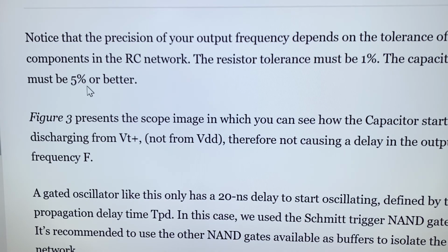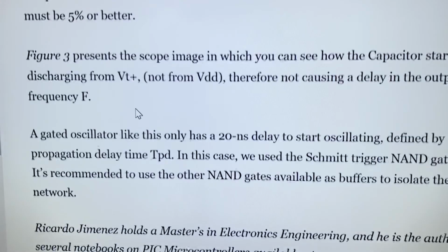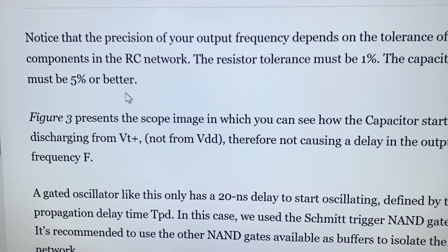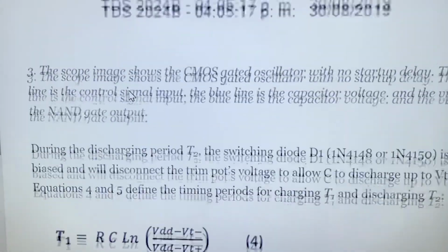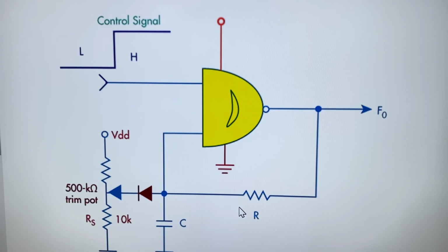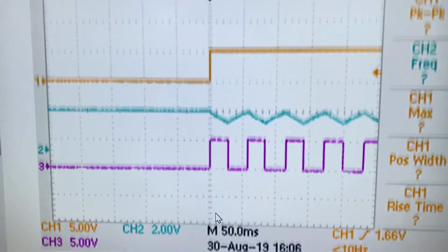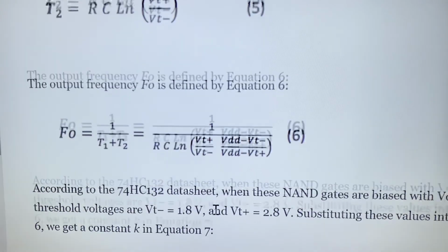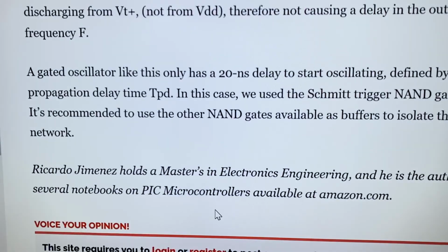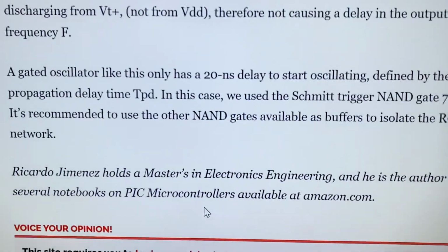So that will change your frequency by 20% in this formula. So that's something you have to consider. And of course, for the resistor in the feedback, if you use a metallic resistor with a very low ppm, parts per million, it'll make your design more stable. Okay, and so that's what I was willing to explain about this design.